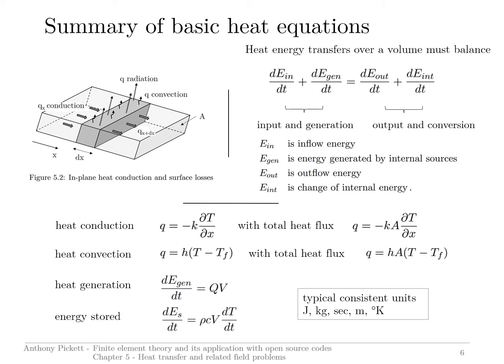So to get it to run, you have to replace conductivity with permeability, you replace temperature with pressures, and exactly the same finite element solution is performed to predict the fluid flow rates, for example, under this dam structure. So it's just to give you an idea that we can really use the heat equations that we develop for other field analysis problems.